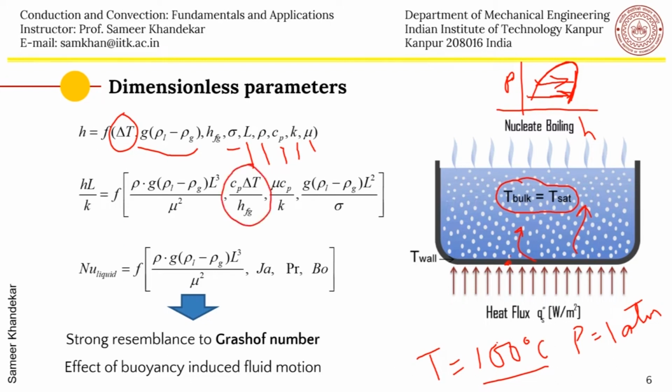Mu Cp by K is well known. This is the ratio of the momentum flux and the energy flux, the Prandtl number, which is well known to you. And then here is the scaling of the buoyancy force to the surface tension force. The buoyancy force wants to take the bubble upwards, and the surface tension force is trying to hold the bubble. So the ratio between the two is called the Bond number.